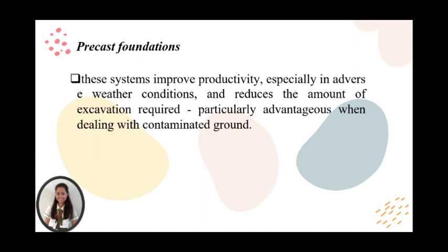The advantages of this method are: the precast concrete foundation is constructed in a controlled environment and hence it follows strict quality control. Second, the precast concrete foundation units are stronger and lighter when compared to other competing materials. And lastly, employing precast concrete foundation construction techniques helps to minimize the construction period.